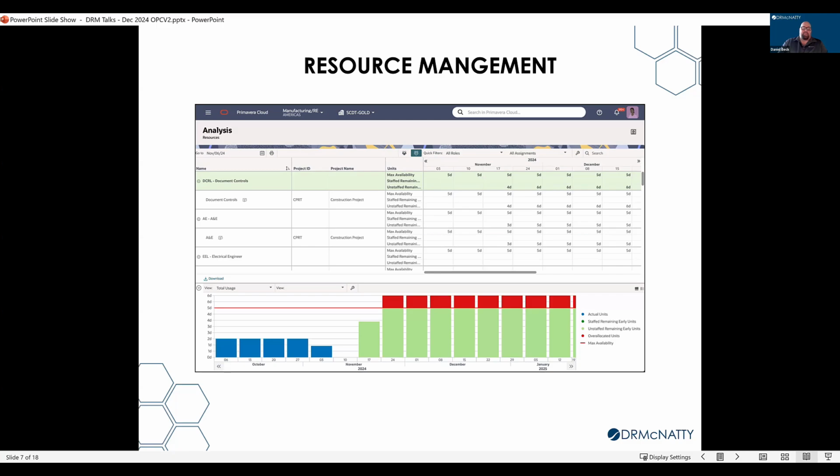Great. And you had mentioned, we've talked about it. Obviously, we know it does scheduling, but does OPC support multi-project scheduling and portfolio management? Yeah, so within OPC, there's a section called programs. So programs basically will replace what you would traditionally do in P6 by opening up, say, 5, 10, 15 projects all at once. A program essentially will capture all those projects. You can manually add those in there, or you can have a filter set. So anytime a project satisfies that filter, that project automatically gets put into that program.